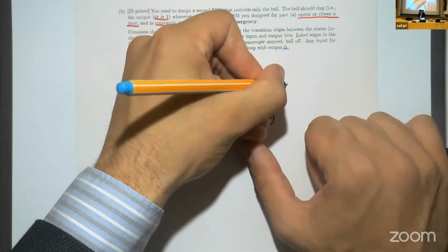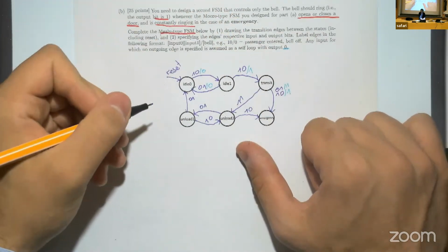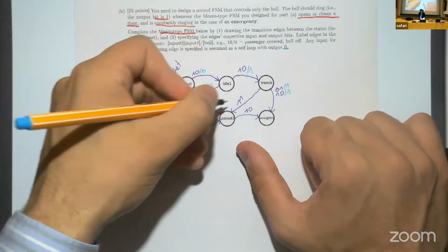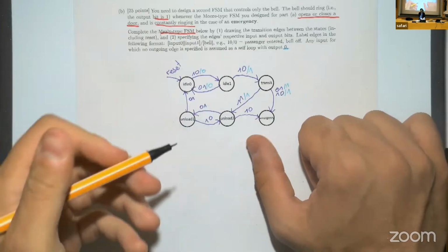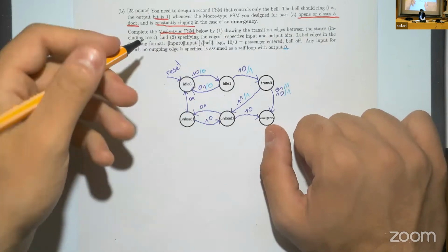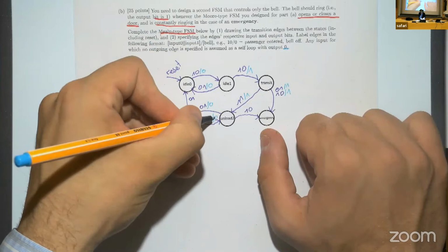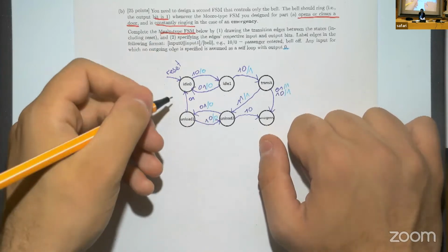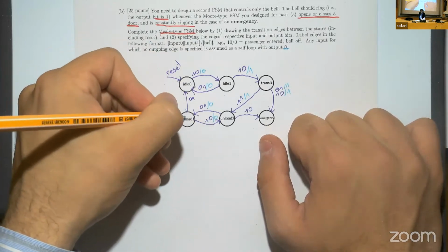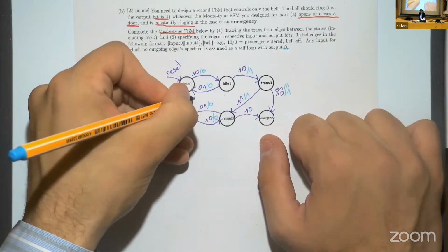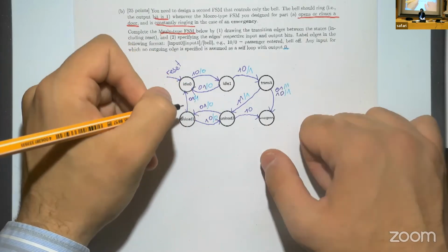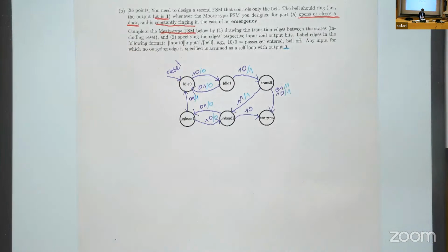So certainly both of these should be an output bit 1. If you go from transit into unloading, you should have a 1 because we open the unloading door B. And then between unload states again, nothing changes. So no bell ringing. And between unload and idle, we do have a bell ringing because we close door B and we open door A.